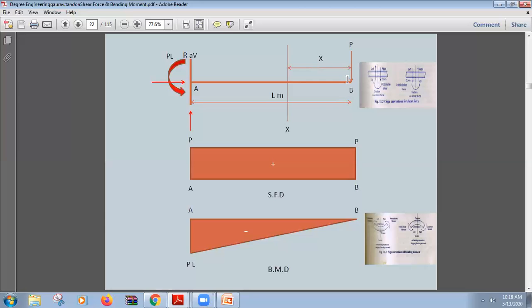Now you will see that P is 10 Newton. So you have drawn at point P 10 millimeters, because I told you to take a suitable scale, 10 millimeters, sorry, 1 centimeter. So you can take a suitable scale. You have taken a suitable scale, 1 Newton is equal to 1 millimeter. So this way 10 Newton will represent 10 millimeters. So this way we have found 10 millimeter. Now we've got point P.